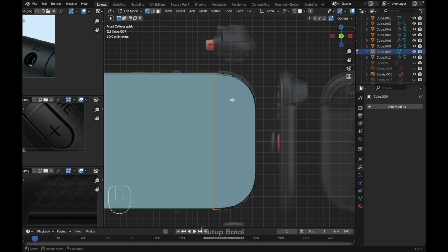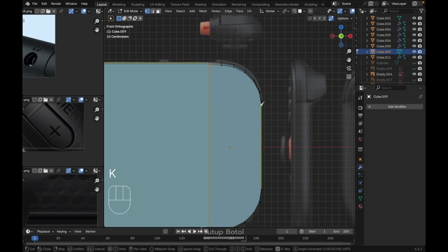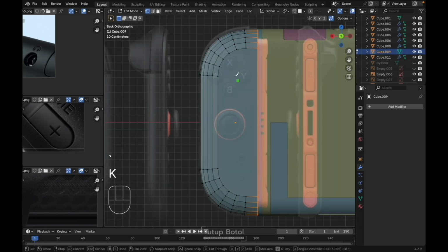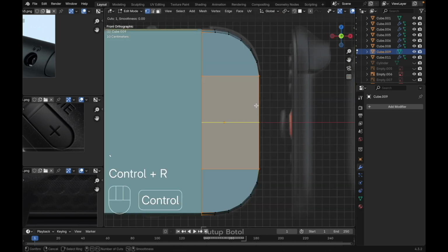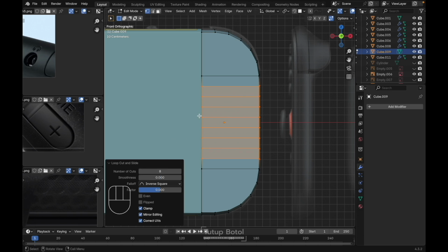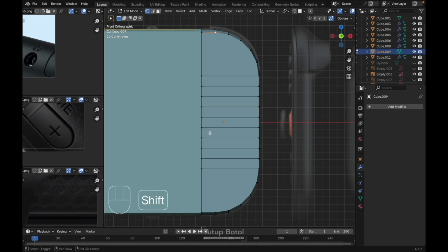Then let's fix this mesh, press K, click here, X like this, K, click here, press X till here, then press spacebar just like this. Do the same at the back, press Ctrl R, put a loop cut here. I'm using 2 cuts here. Click this vertices and this one, J to join.